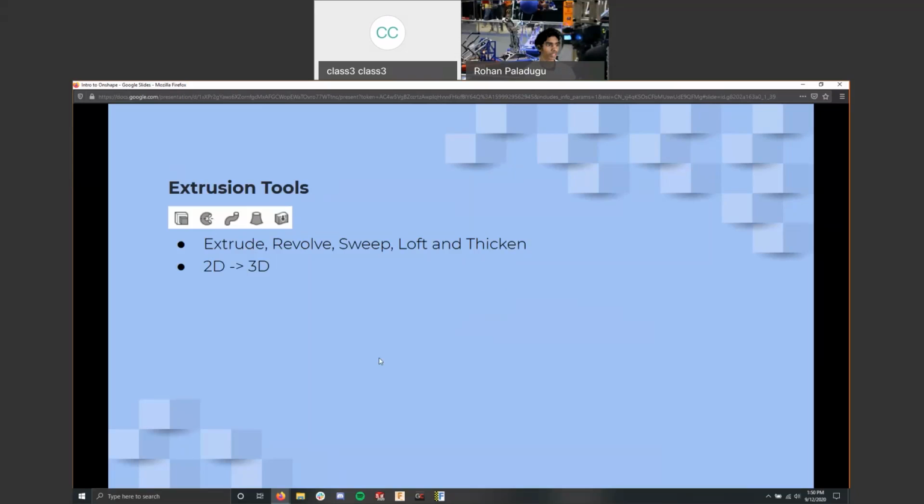So let's say I want to create a drive rail tube. I have my sketch of the cross section of the tube. That's just a rectangle, and then I have another smaller rectangle in there to represent the thickness of the material. I've dimensioned everything, and I think, all right, that's the sketch, I'm good. So now I exit out of the sketch, and Onshape's like, all right, here's a sketch.